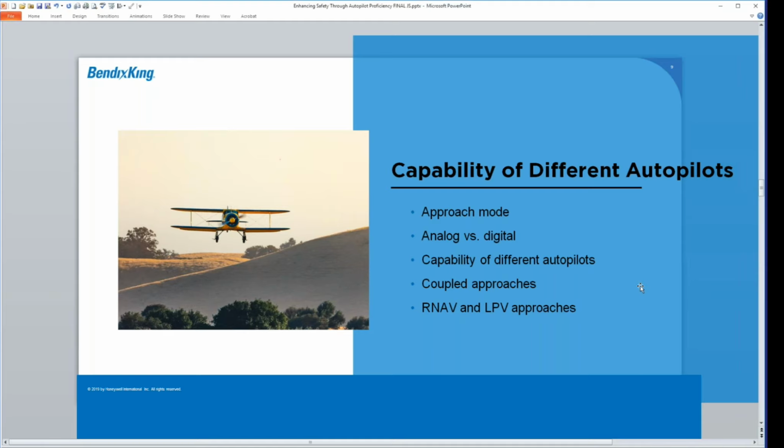capability there as well. If you know that your course to the outer marker is 183 degrees, there you go. You dial that in on the autopilot, and away we go. Same thing on commanding that descent. Once you've got the needles centered, you can engage the autopilot, and it'll actually continue to fly you on that course and on that vertical speed, keeping everything centered. Obviously, you're still watching it, but it's still a great pilot aid.